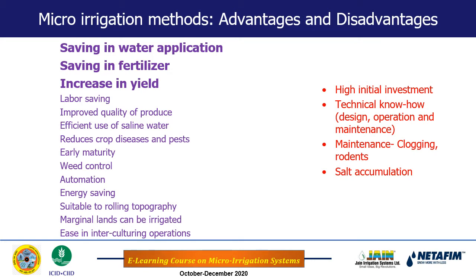But when it comes to the field, we have to distribute the water through a network of field channels, and there are distribution losses. And with the surface irrigation layouts, that is border, check basin, or ridges and furrows, there are unavoidable application losses as well. But in drip irrigation, we bring water from the source directly up to the root zone through a network of pipes, so there are no conveyance losses.